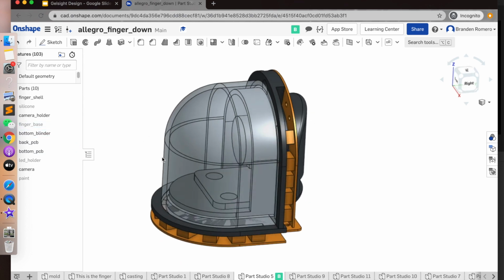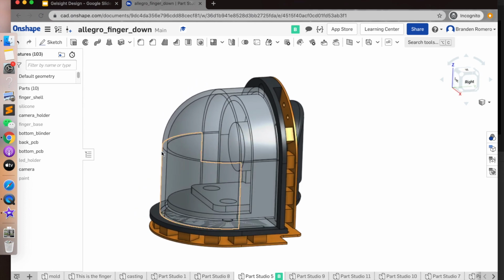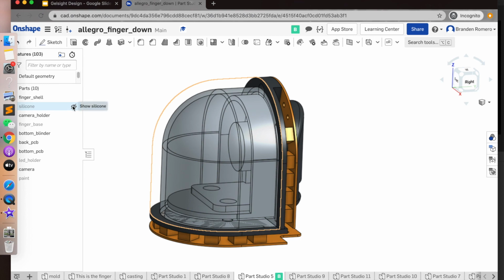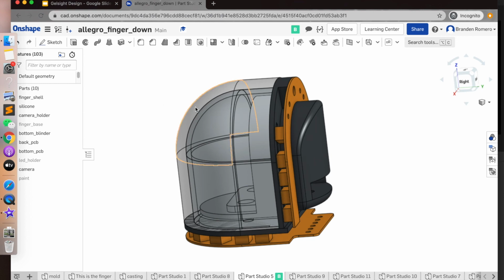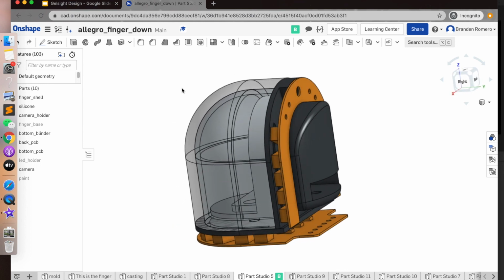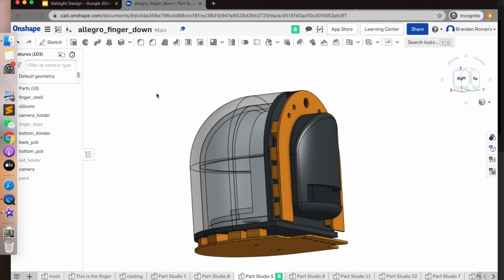This plastic shell is cast. I could talk about this more in the manufacturing part. Then we coat that in a 2mm thick silicone layer. The plastic shell itself is only 1mm thick, but the material we're using is pretty rigid, so there's no deformation if you press down too much on it, at least with the force limits of the hand. Then our silicone is 2mm thick. We're not sure if 2mm is too thin or too thick yet. It's something we haven't tested, but we would like to look into it more in the future.